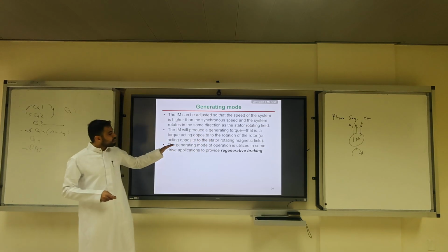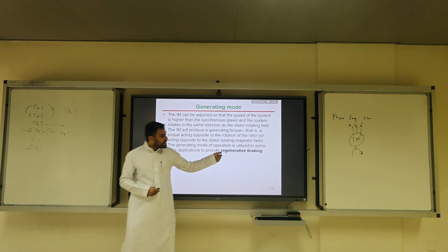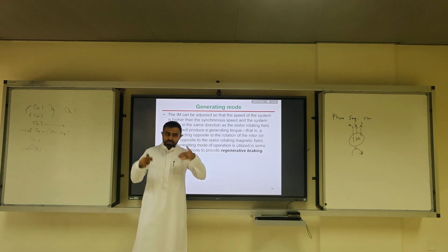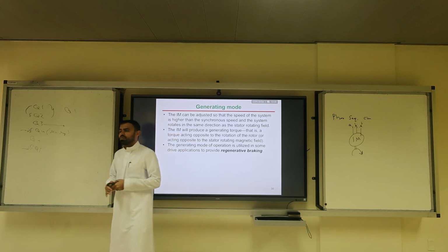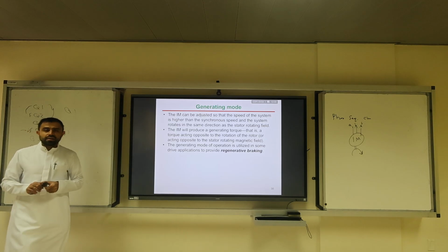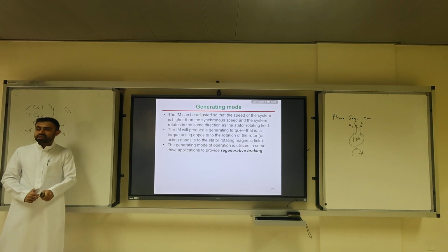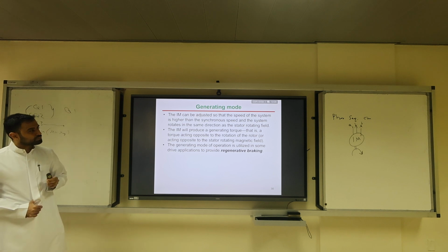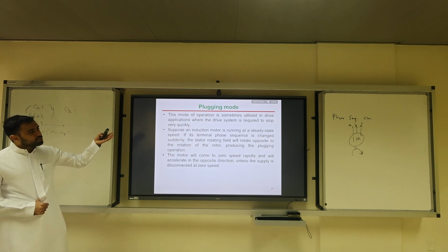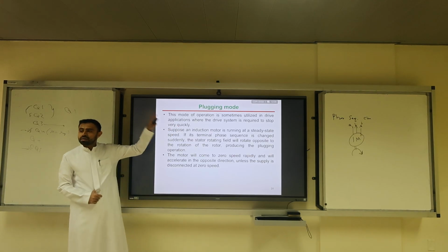Again, the generating mode of operation is utilized in the application we call regenerative braking. It's braking, but it regenerates electricity. And this is the basic concept of hybrid EVs. The hybrid vehicles utilize the regenerative braking to maintain their small batteries. The batteries in the hybrid EVs are not as big as in the pure EVs. Plugging mode is utilized where the drive system is required to drop suddenly.